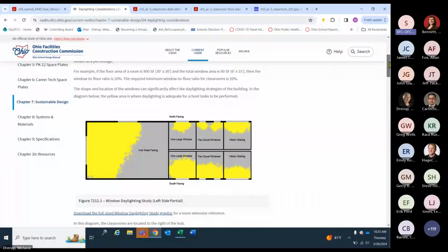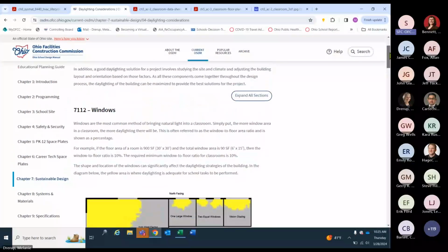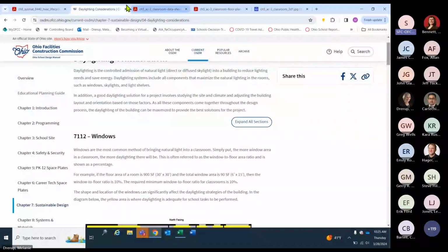Daylighting considerations are important, not only in supporting LEED initiatives, but are also crucial considerations in the creation of learning environments to help assure students have adequate access to natural daylight in classrooms. The minimum glazing requirement has been increased from 5% of floor area to 10%.